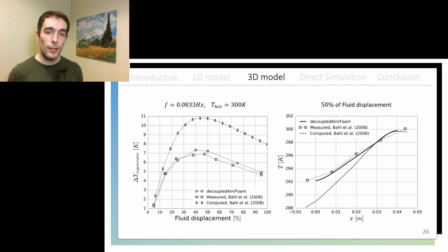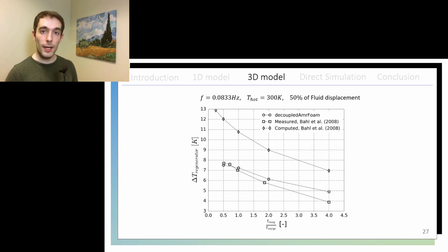First one would be impurities in the magnetocaloric material, in gadolinium. A second one would be the lack of modeling of the heat losses to the environment, which I didn't include either. So to me, the most compelling argument for that discrepancy would be the third one, a simplified representation of the magnetic field. I applied an instantaneous and homogeneous magnetic field on those plates. So I think the following slide further proves the importance of correctly modeling the magnetic field in the regenerators.